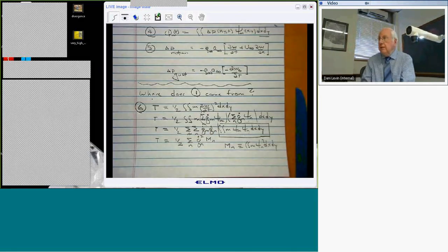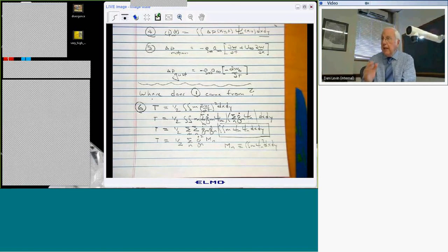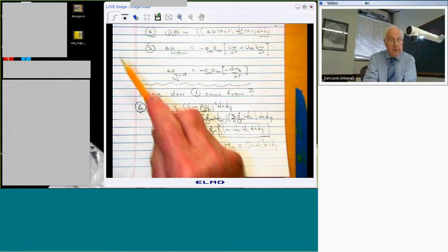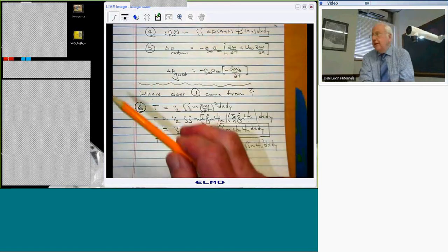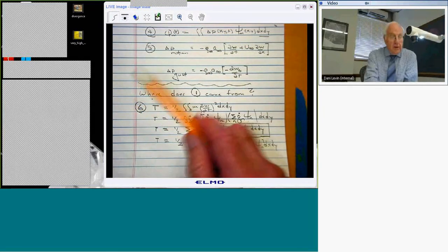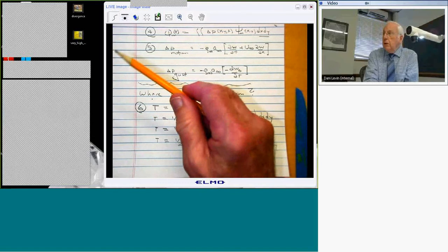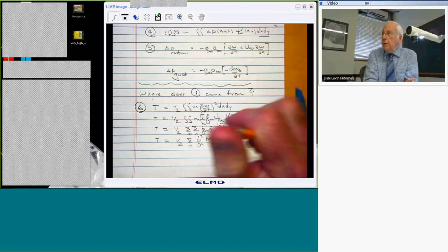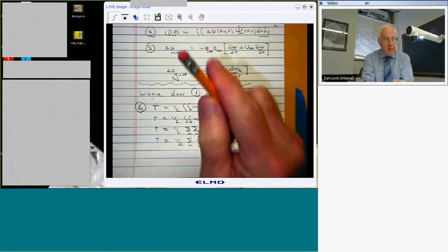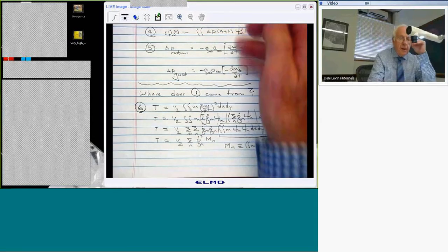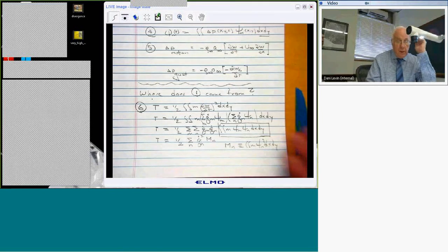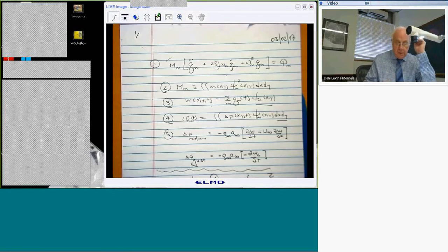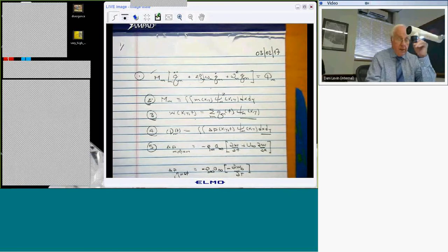Okay. So if I use Eigen Modes, I have orthogonality. I can always generate a term like this. This term, of course, I make up, so you can't dispute that. This term, it's a little bit more difficult. It turns out that for any linear elastic body, this is still correct. But it's probably at this stage, yeah, this term I'm talking about.